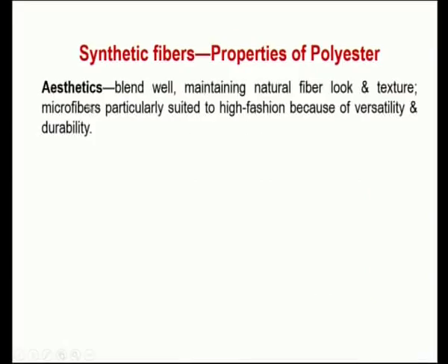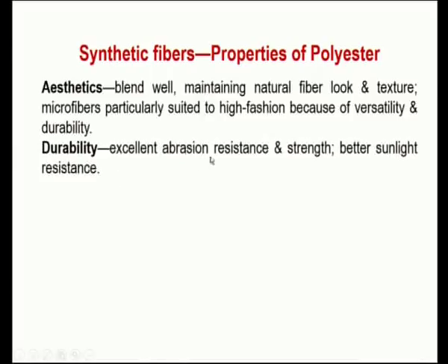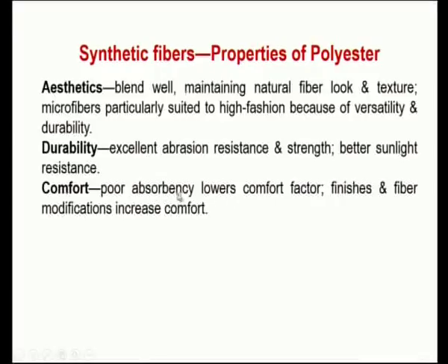Properties of polyester, again aesthetic property, which is that it blends well, maintaining natural fiber look and texture. Microfibers are particularly suited to high fashion because of versatility and durability. Again durability, which is excellent abrasion resistance and strength, better sunlight resistance, which is very important. If it undergoes degradation in sunlight or environmental conditions, it may not be suitable, but it is environmentally stable. And comfort: poor absorbency lowers the comfort factor; finishes and fiber modifications increase comfort.